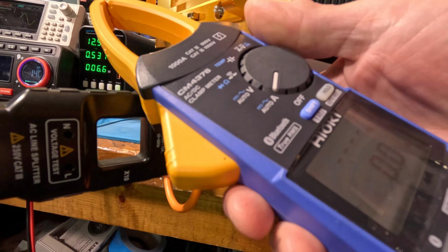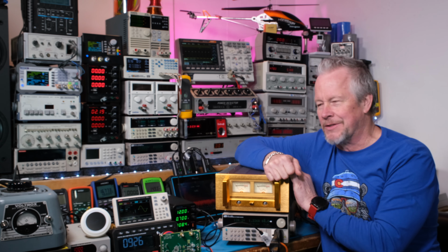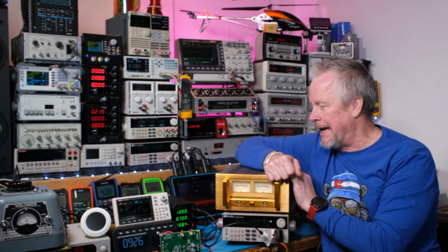Okay, guys, so in a power supply, like in a Class A amplifier, the low frequency switcher is nice and toasty warm, that's why I'm leaning on it, because my lab is 12 degrees C, and the Class A is a toaster oven. So I'm actually able to kind of lean on this bad boy. We're pulling around 100 watts, and we're not doing anything. It's just no signal going in. So there you go. It's about a 60 watt amplifier with 30 watts per side. So 60 watts total, both sides. And right now 100 watts, no signal. So you can see how inefficient a Class A amp is.